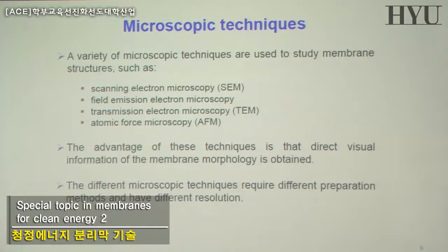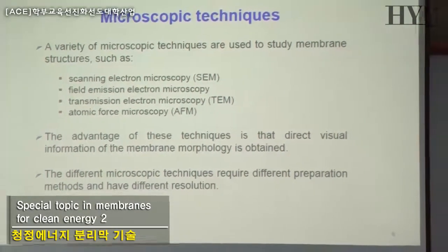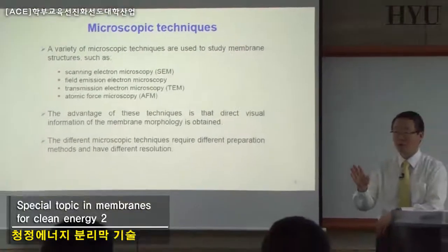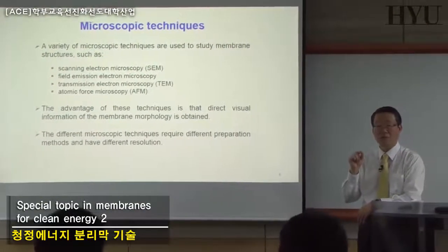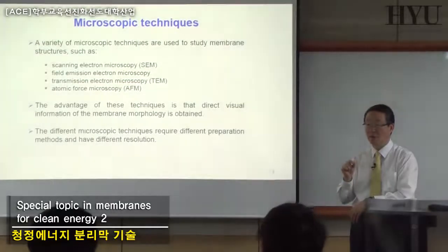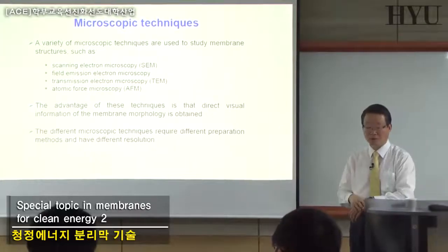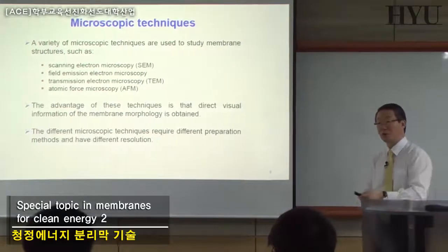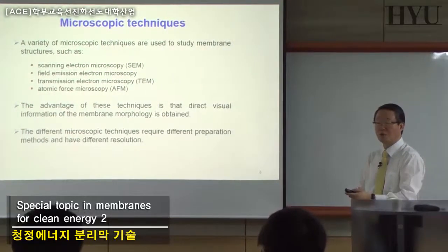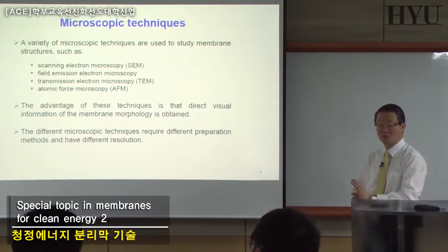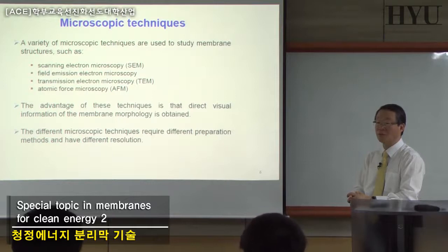So when you report the property of the membrane, you can report LP rather than the flux itself, because flux depends upon the applied pressure. Unless you apply the same pressure, like 10 bar or 5 bar, whatever you report. But usually the pressure differs. Therefore, if you are developing membranes with different porosity and so on, it's much more convenient to report the permeability rather than the flux.